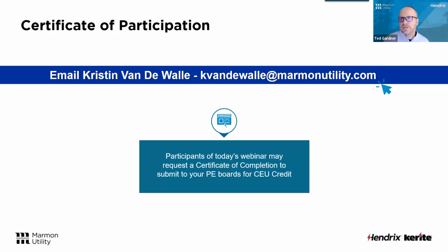HDPE is our standard product. It's always been our base product, and we've made that since the 50s. XLPE will tend to be a little bit more rigid, but more than anything, it has a higher emergency rating. We rate it at the same 90C as our 90C HDPE, but you can get another, I think it's 20 degrees of emergency overload before it causes any kind of damage to that covering.